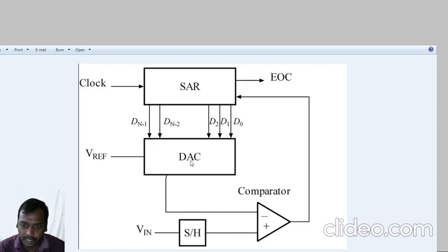Again the DAC output is given to the input of the comparator. Again it compares with 1 volt. So then it is equal. Okay. Then the output is given again to the successive approximation register. Here again it sets the D1 bit, 000010, then 00000011. Okay, the next bit will be set.